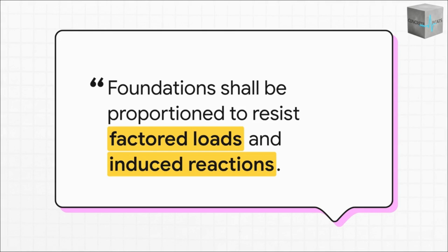It sets up the most basic rule of safety. Factored loads just means we take the expected loads, like dead and live loads, and multiply them by safety factors to account for any unknowns. And the rule is simple. The strength of our foundation has to be greater than those factored loads. It's that classic capacity versus demand relationship that drives all of structural engineering.